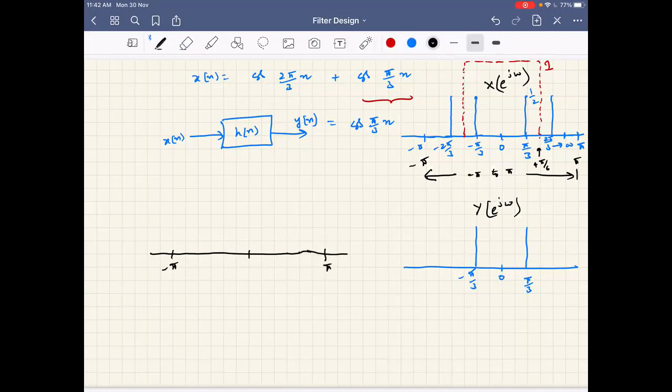Okay, right. So this is one kind of filter, wherein the filter passes some frequencies and attenuates some other frequencies. This passes which frequencies here? Based on the frequencies which the filter passes, it is referred to as a low pass filter, high pass filter, or band pass filter. Here, the frequencies near 0 in the discrete domain we consider low frequencies, and those close to pi are high frequencies, because of the nature of the oscillations that they generate in the corresponding time domain signal.